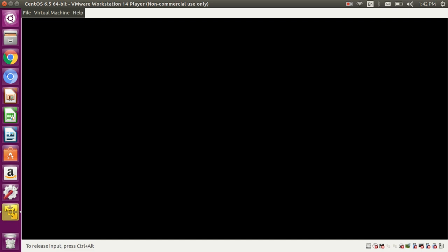This is directly given to the AND gate. That means this enable is given to the AND gate. Whenever this is 0 or this is 0, the output will be 0. Whenever the clock is 0, the AND gate will be off by default. It is that simple. Whenever the clock is off, the AND gate is off. So by default, whenever the clock is 0, we will not get any 1 there.